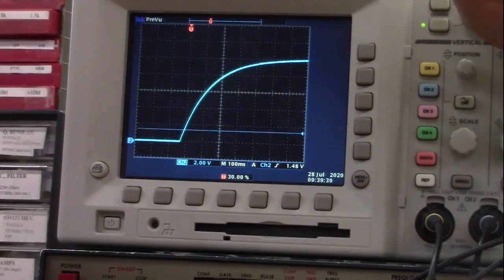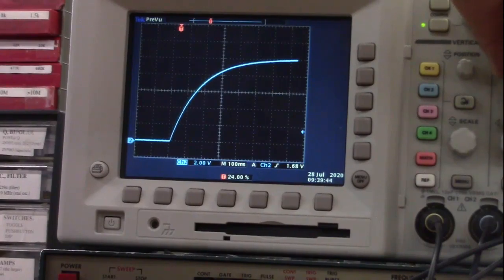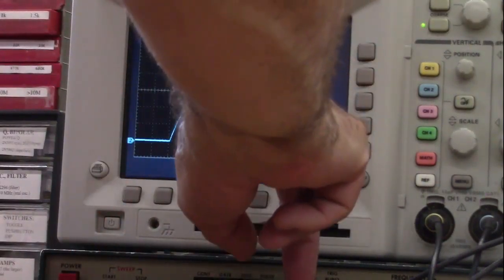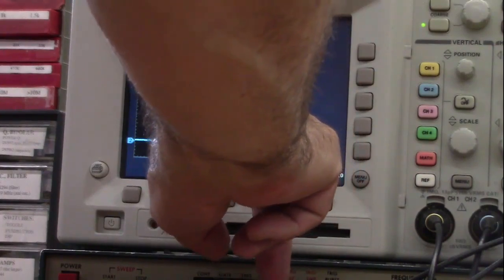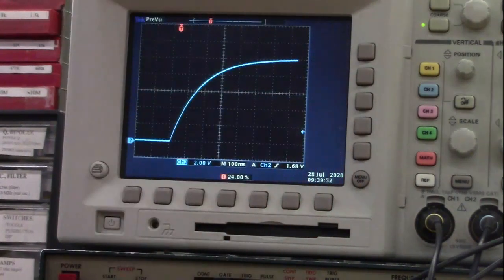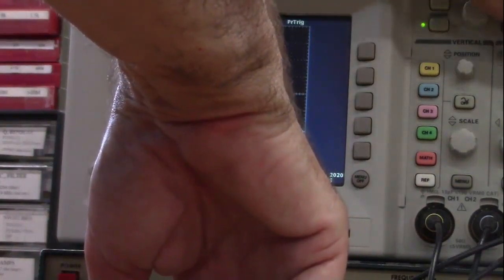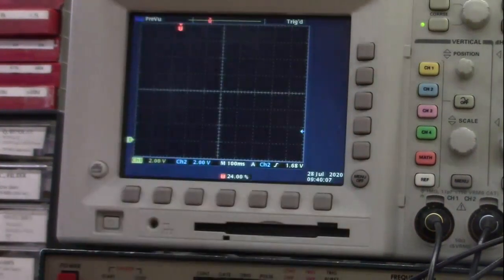Let's go ahead and position this so it's easy to see how long it takes. So it looks like we're up at 10 volts, maybe out here, which is 1, 2, 3, 4, 5, 6, say 7 divisions, somewhere around 700 milliseconds. Now we can compare that to the current source. Let me try and release both buttons at the same time.